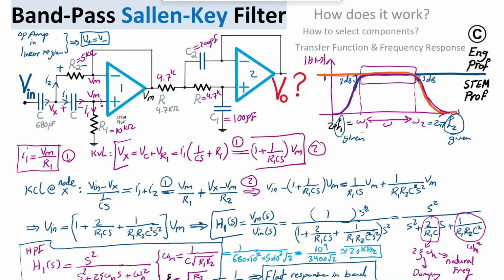And if they are FET input, the leakage current would be very low, so low offset, low noise, and good gain bandwidth.